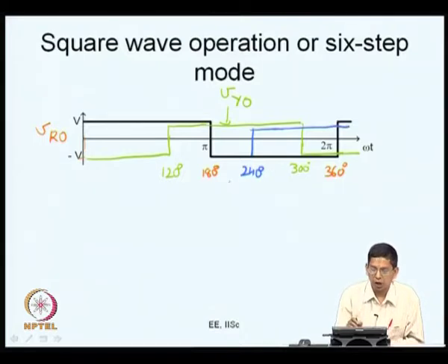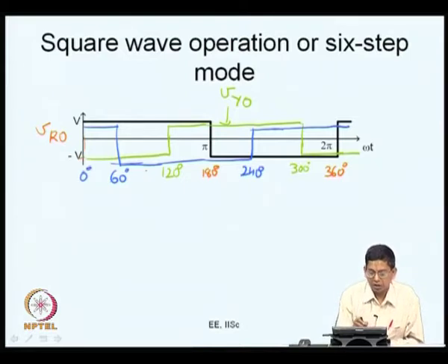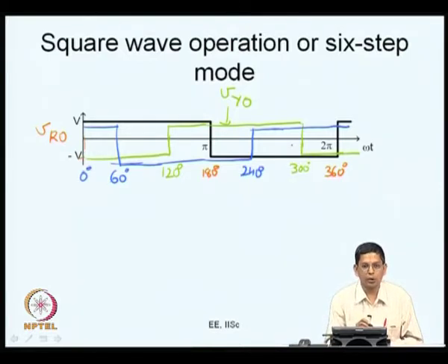which is 240 plus 180 is 420, up to 420 it continues to be high, and it is low for 180 degrees before 240, that is up to 60 degrees, this is low. So, at 60 degrees it basically switches from high to low. So, this is how you have the 3 pole voltages.